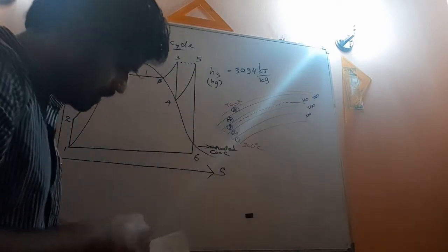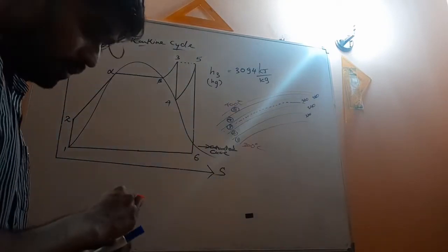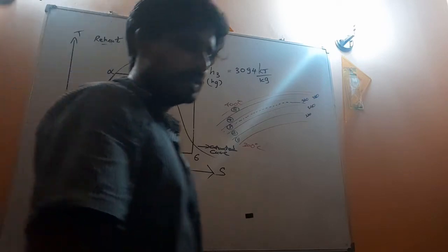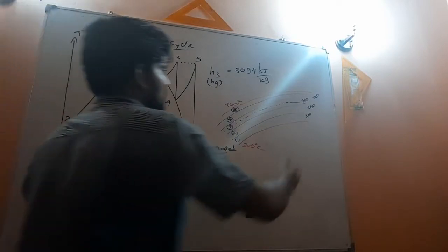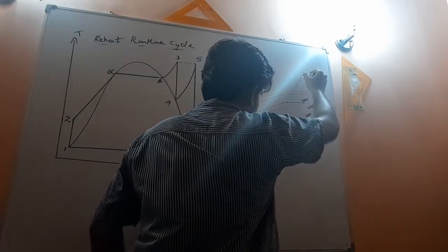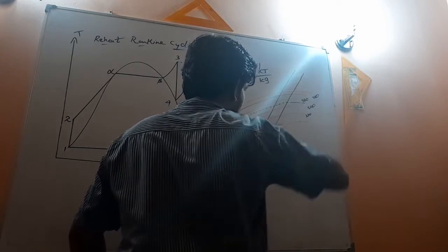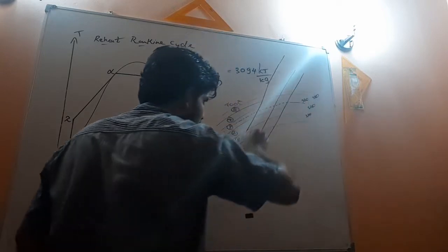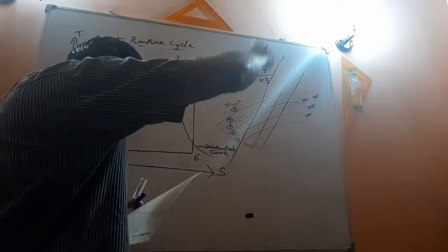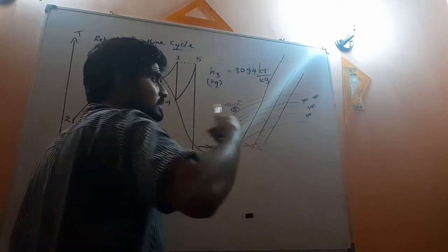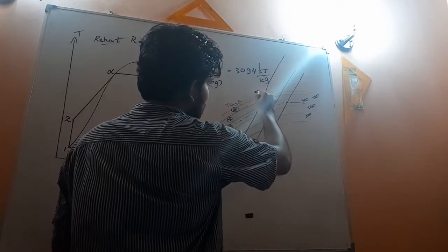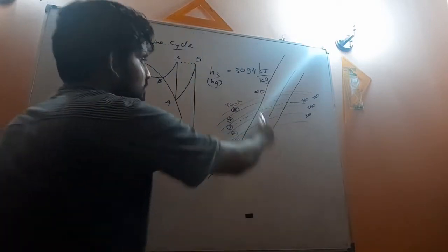350. And so now you have to consider the pressure lines. Again, get the HS chart. In the HS chart, you have pressures like 10 bar, 30 bar, 40 bar, like that. You have some lines, right? So those lines are representing the pressure. So let's say this is 40, right? So this is 40 bar line.